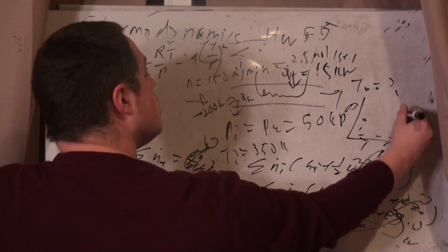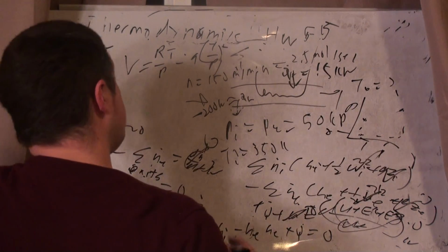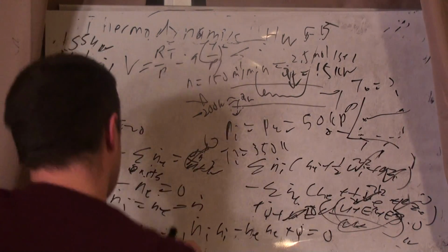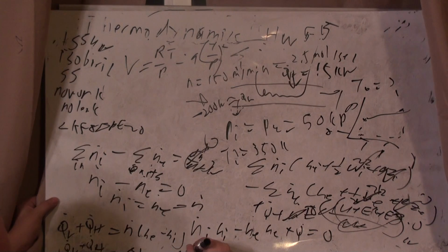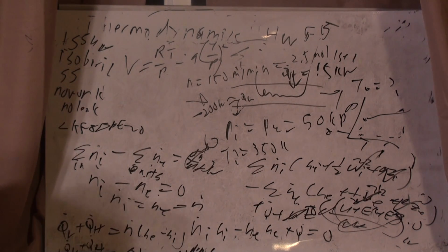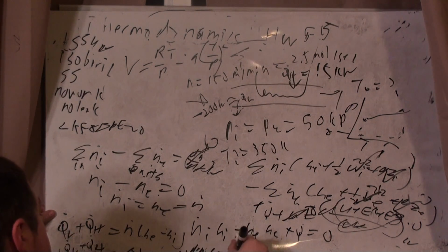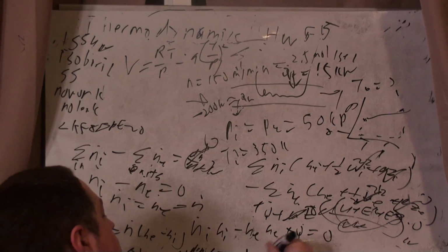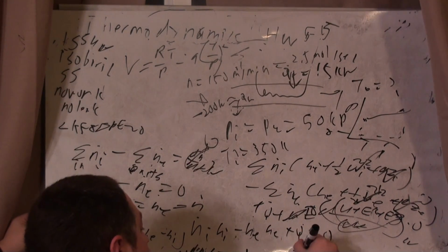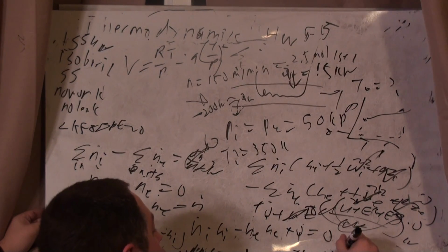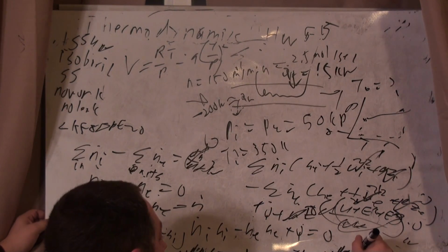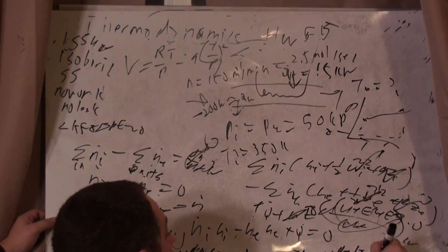I'm going to go down to 0 and up, so this is 0, that's my ideal gas. And so this becomes minus delta H departure function at the inlet, so Ti and Pi, plus delta H of an ideal gas, plus delta H departure of T exit, P exit.